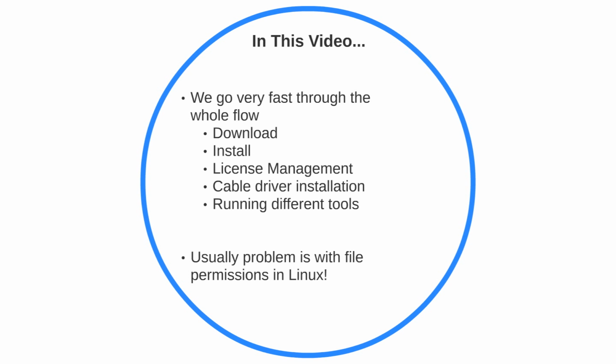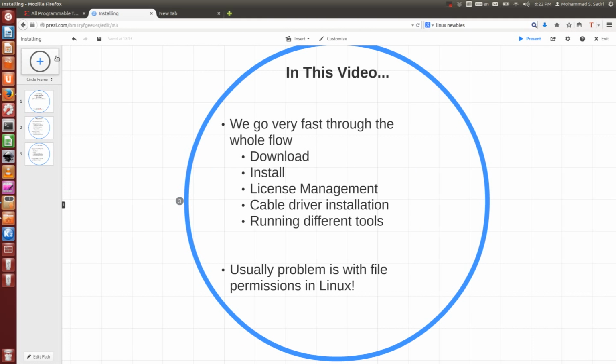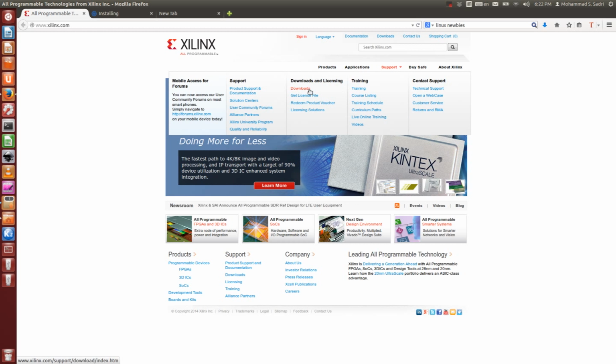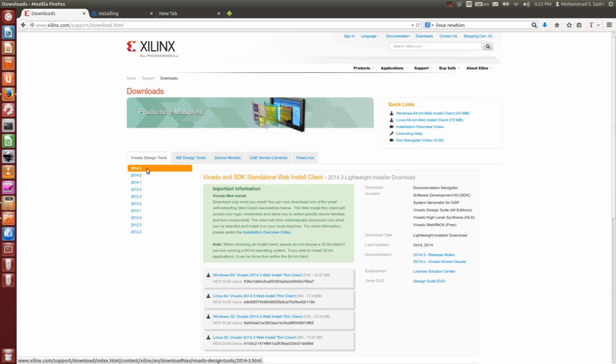So here, I come to the Xilinx website, and then Support, and then Downloads, and then we have Vivado Design Tools and ISE Design Tools. These are all Vivado design tools. The latest one at the time of recording this video is 2014.3, and here you have some quick links. You click on the Linux 64-bit web install client, which is actually 72 megabytes, and this is an executable that I download and run on my system.